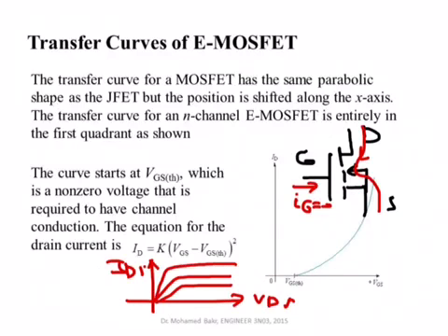So it is either a linear function of VDS or it is not dependent on VDS. In the book of Floyd, they assume that we really work in the saturation region, so the current is not dependent anymore on VDS. The current only changes when you change VGS: VGS1, another value of VGS, a third value, and so on.